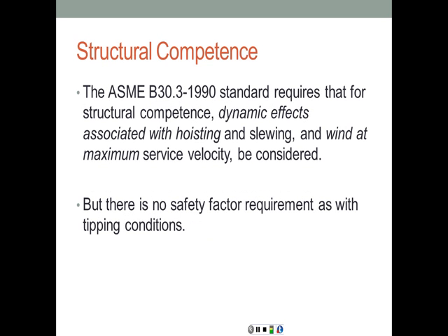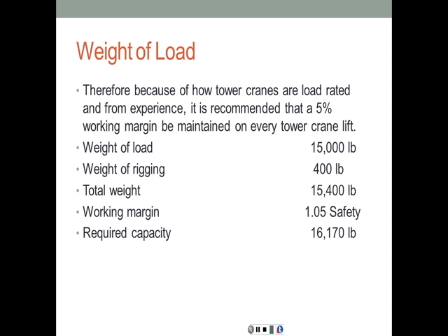Again, the American Society of Mechanical Engineers standards require that for structural competence, dynamic effects associated with hoisting and slewing and wind at maximum service velocity be considered. So there's no safety factor requirement as with the tipping conditions in this case. It's again left to the consideration and the expertise and the experience of the operator and the project manager, who should stop the operation if there's any danger to people or to property.